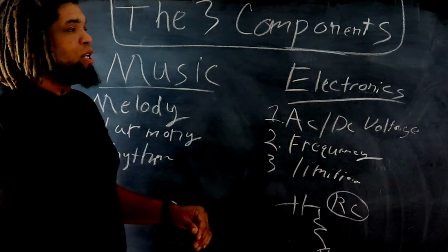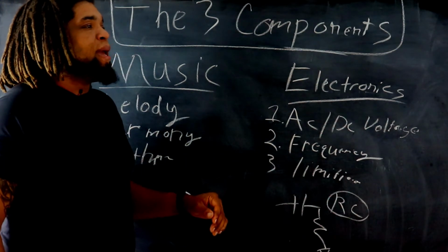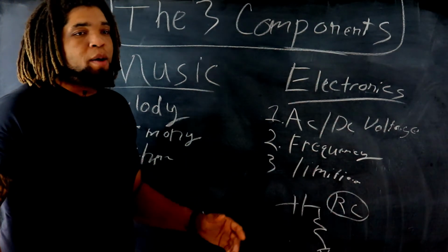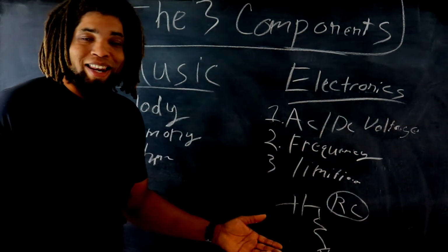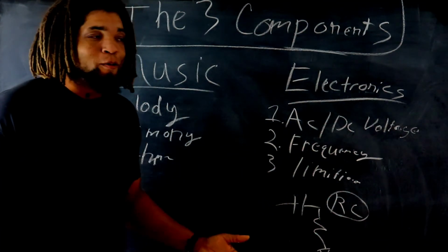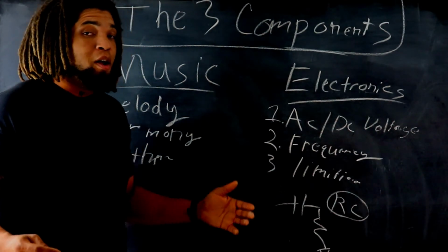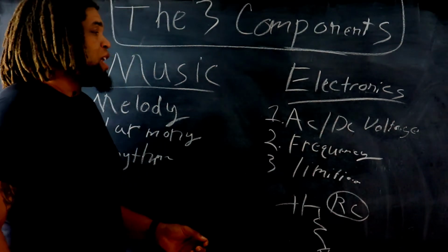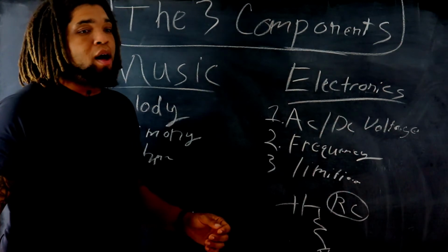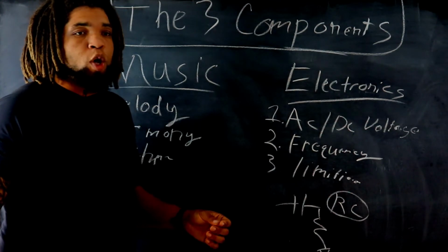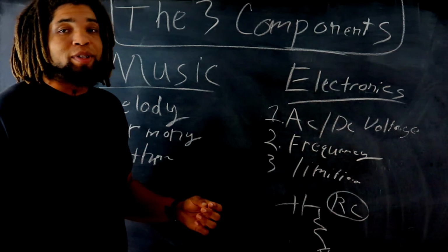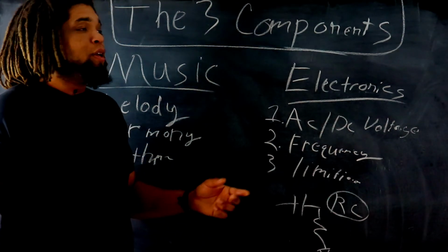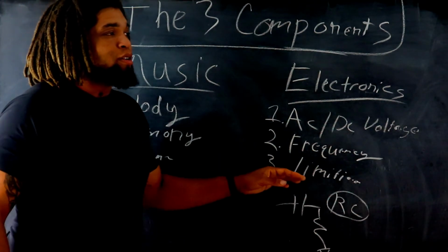Maybe we only want it to be able to pass frequencies up to 20 kHz, which is very common in audio, for more reasons that we can go into later, but primarily because we're not trying to absorb any other frequencies like RF frequencies, AM frequencies into our electronics.